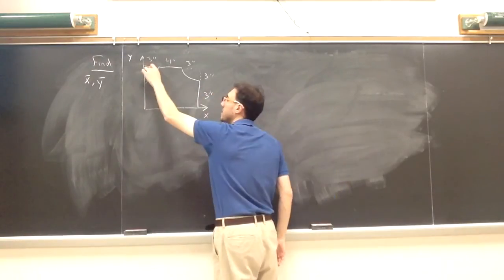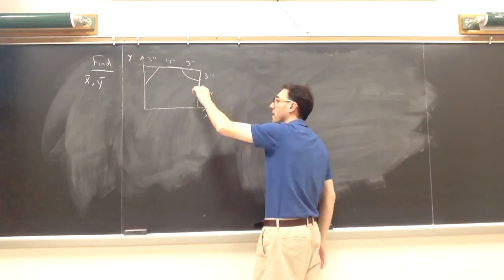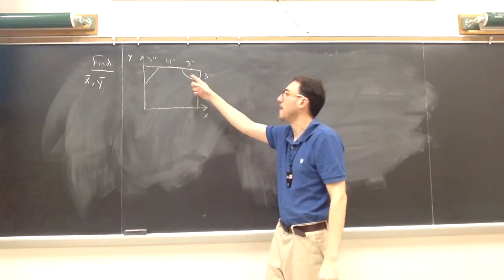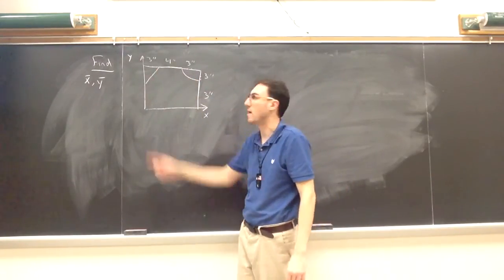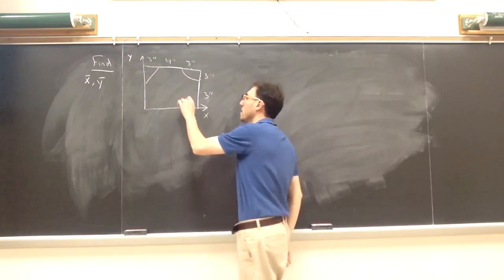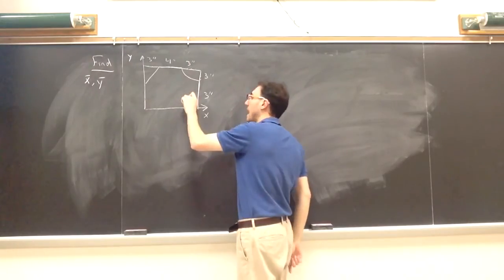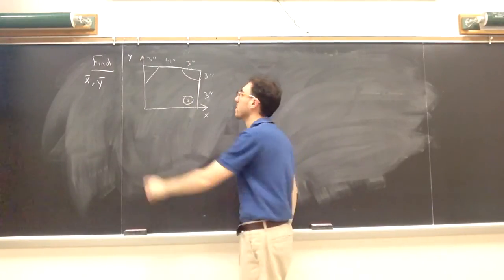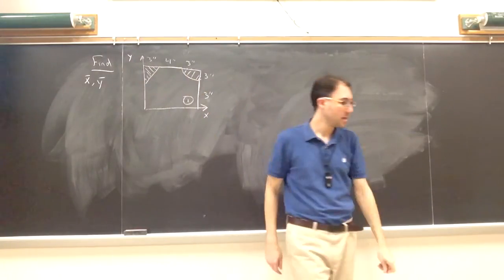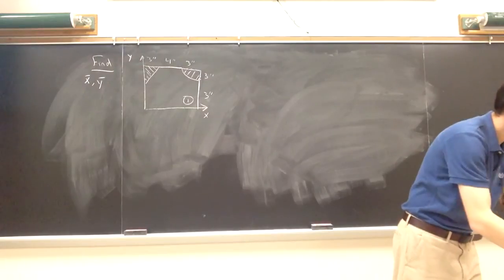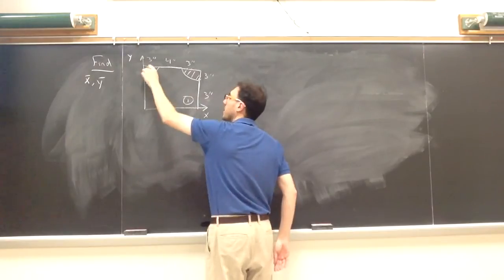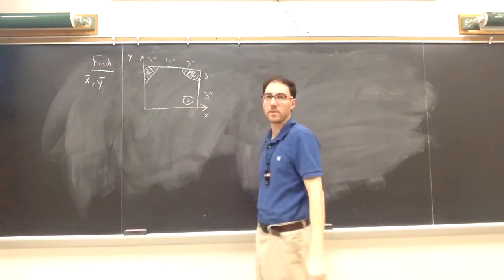This entire outer rectangle here as a solid shape, and then to make up for the fact that we included stuff that wasn't supposed to be there, we'll cut out this triangle and cut out this quarter circle. So I'm going to call that outer shape, that rectangle, shape 1. And then I'm going to remove this and remove that from it. And so it lines up with my notes, I called the triangle piece shape 2, and I called the quarter circle shape 3.